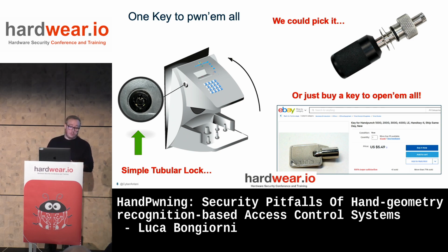But anyway, tubular lock, what does it mean? It just means security through obscurity compared to a classic pin tumbler lock. Here, what you need is either a tubular lock tension wrench and a needle to push back the pins and try to open the lock, or just a classic tubular lock pick, like in the image up there. Or the third option was Googling, because I'm a lazy guy and even a lazy lock picker in this case. So I checked around if there was some sort of key I could ask the manufacturer to remake, giving them some code. Usually it sometimes happens like that.